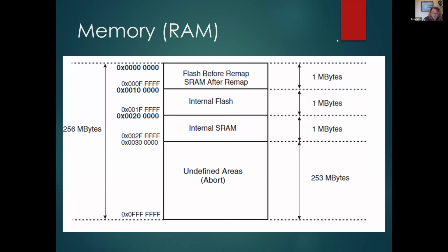But one thing to note here on the slide as we look at the addresses without memory and addresses that can be remapped onto other addresses. Embedded software engineers deal with pointers very closely. Not only is RAM sometimes a precious resource, memory is a very real physical resource. Pointers to memory aren't amorphous blobs. They point to specific memory chunks in the hardware. And those registers from earlier were memory mapped, as though they were pointers to memory or pointers to pieces of the hardware itself, pieces of the processor itself.